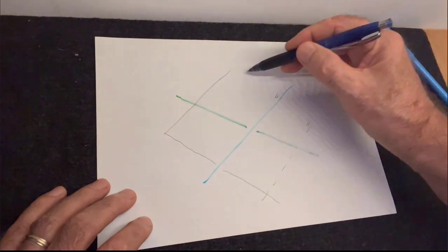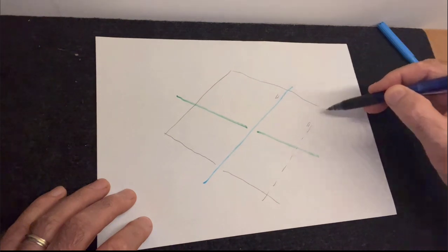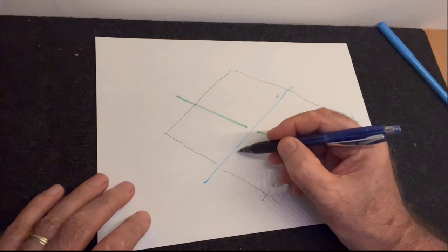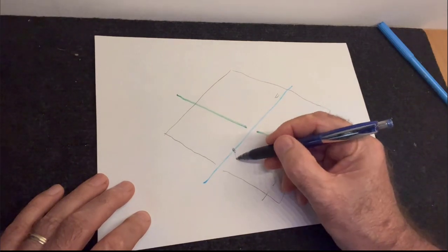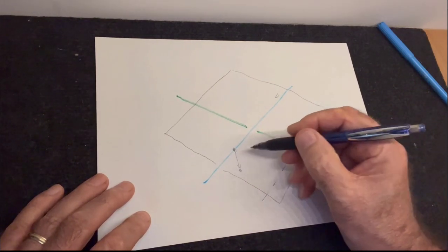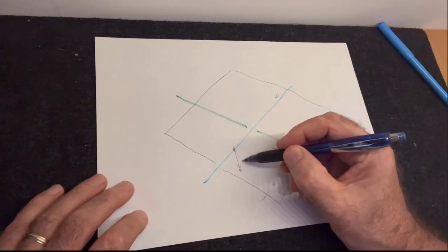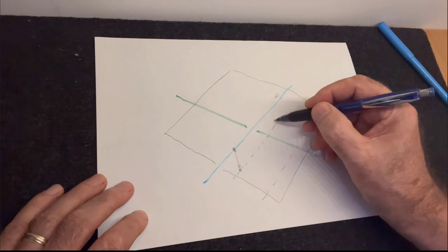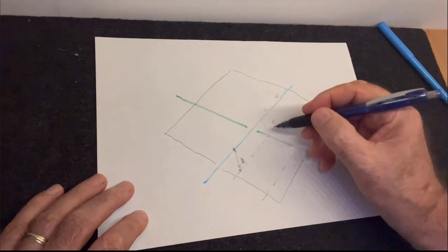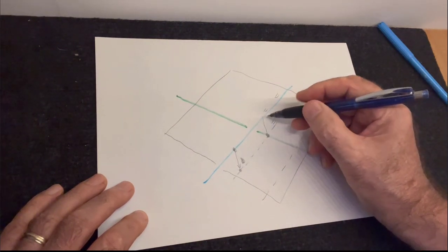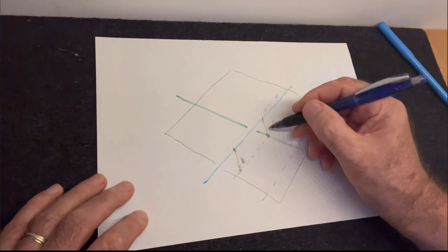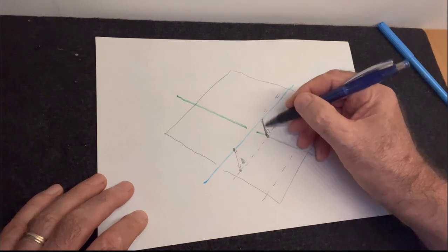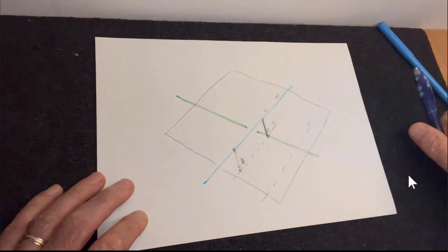Then these two define a plane. We draw that plane. We select a point on the blue line and we project it on the plane. A parallel to the blue line which intersects the green line here, then a perpendicular on the plane and on the two lines, and this is the common perpendicular.